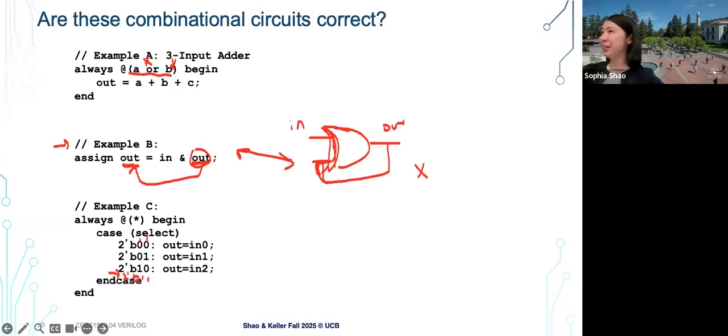So it has certain delays being propagated into the circuit. Yes, because I know in analog, they do something similar. A delay, I guess you can think of it as a buffer, but more like a cascaded buffer. So that's another very common way to add a delay component: just have cascaded buffers. At least in digital circuits, unless you intentionally want something else, for delays it's more common to have cascaded buffers.